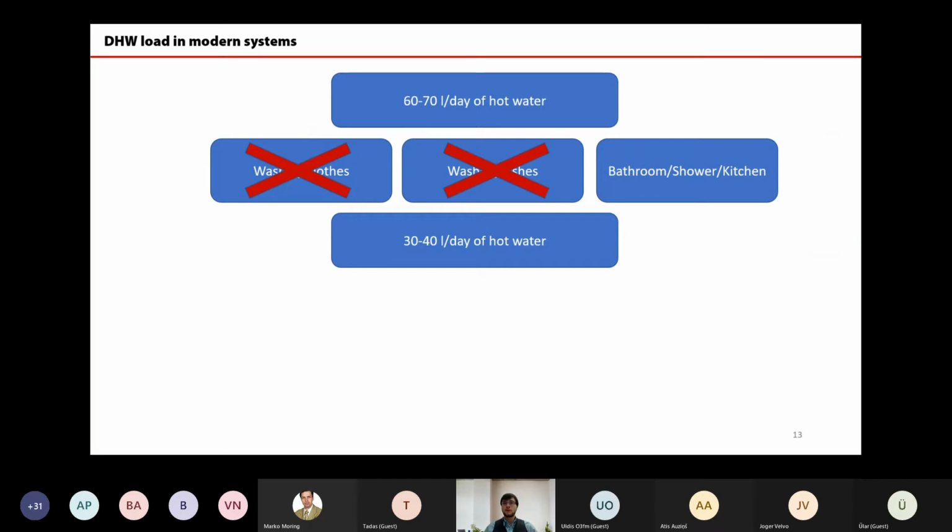And this, of course, needs to be taken into consideration when new buildings are being designed, because if you over-dimension the capacity, let's say you have to make the selection and by the regulation you need 300 kilowatt of heat load, whereas in reality customers are consuming only 150 kilowatt of heat load. That's doubling of your surface margin for the heat exchanger, and that's doubling your basically safety on the valve, because the valve was selected for twice bigger flow rate compared to what you need.